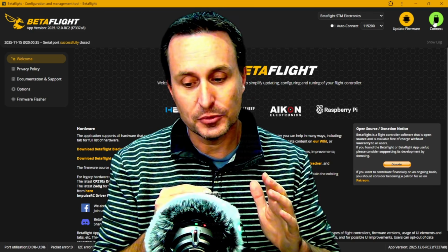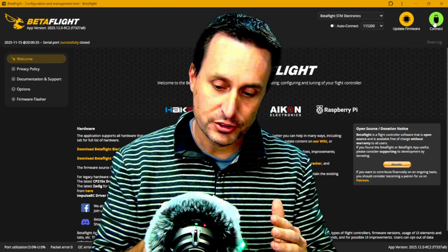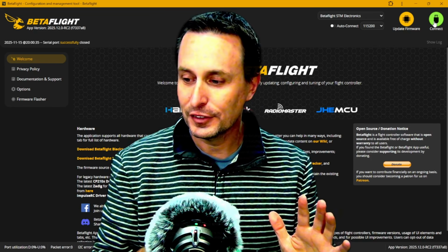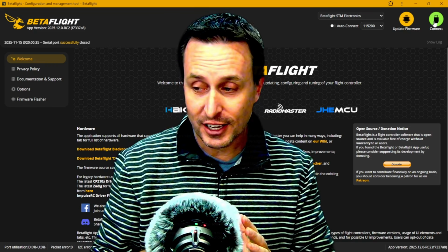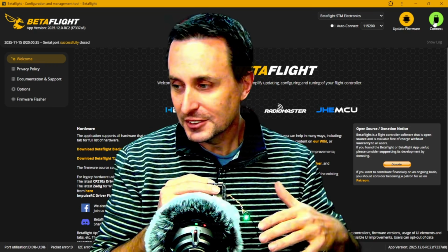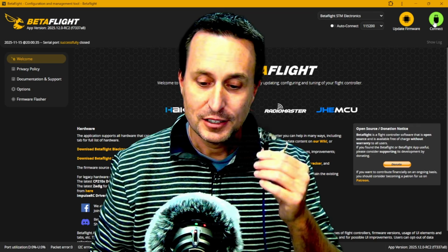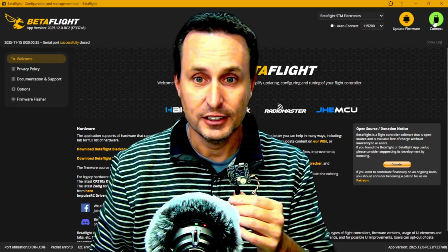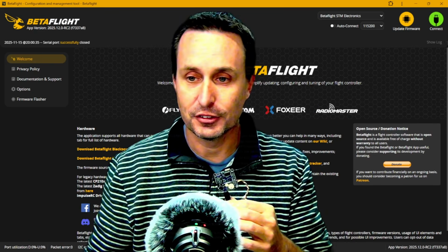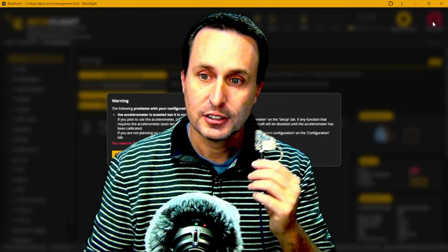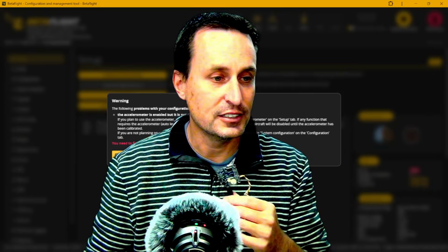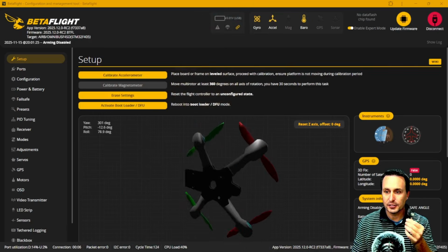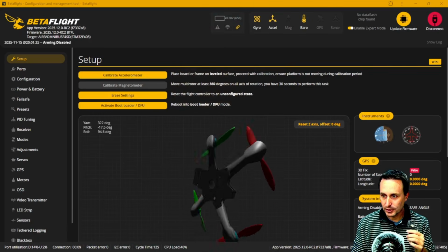We're gonna talk about some PID tuning parameters, S-term versus the PIDs and how they relate to each other, and just a bunch of stuff that is very similar to iNav, but just a little nuance different in Betaflight. But in this one, I want to get you set up at least to get the dang servos moving and the motor working, and then we'll have the next video for the rest of it. So anyways, switching over, clicking on my Omnibus F4 SD card, and then clicking onto here, you can see I have it, it's working, so good test there.